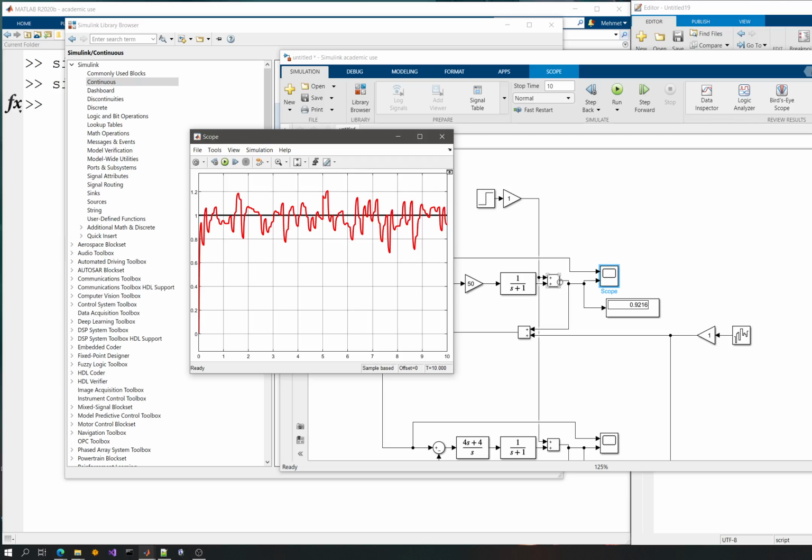It's 100 times, and if you remember, I have changed the power of the noise. If you increase the power of the noise, which might be the case, you have to use frequency domain analysis for that, and it will become worse and worse, since high gain will amplify the noise too. This is, by the way, measurement noise, and that's inevitable in real world applications because there will always be measurement noise, even if you use some filters like Kalman filter or other band stopping or low pass filters.